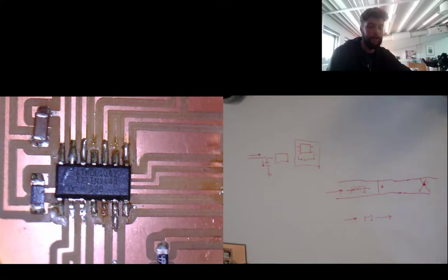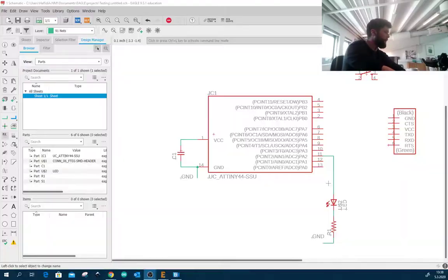If we don't have any resistance of the electrons, we have an infinite amount of current that goes through the LED, and the LED can only handle so much current, right? We only have a certain amount of current that we can conduct through an LED for it to actually work the way we intend it to. So that's why we have a resistor here that is connected to the LED.